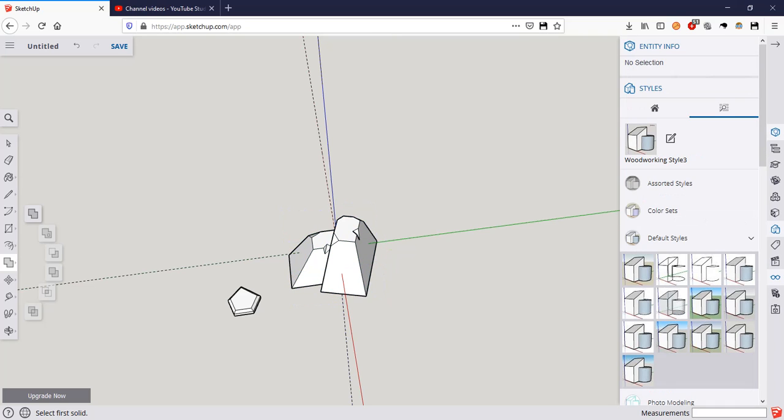It'll do it instantly. Now, if you do upgrade, remember, model big, because if you use it in millimeters, you're going to get holes in your mesh, and Solid Inspector's going to freak out. So scale big, and then scale down at the end, and then export.